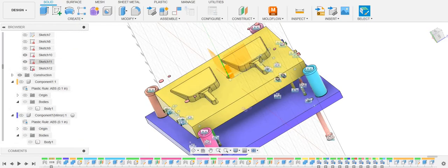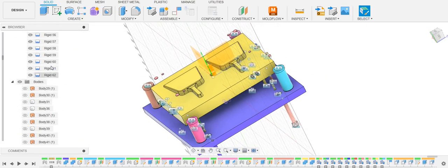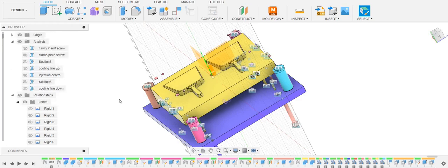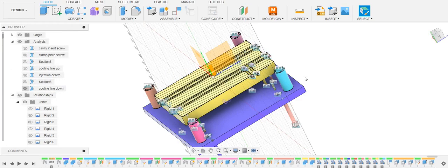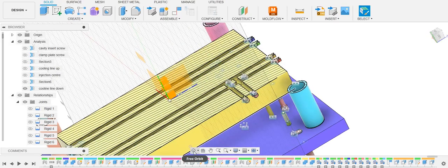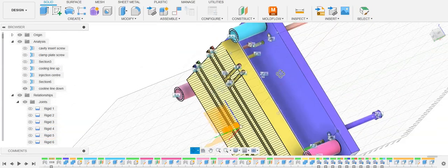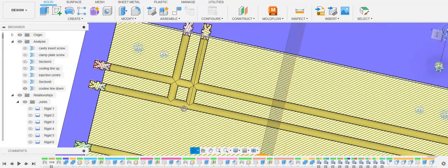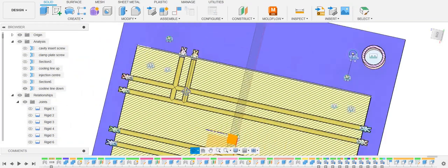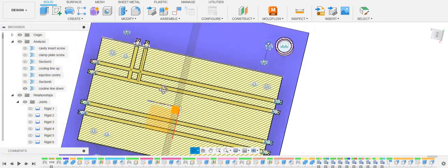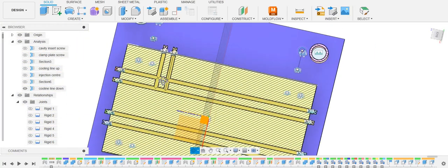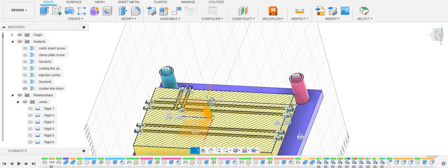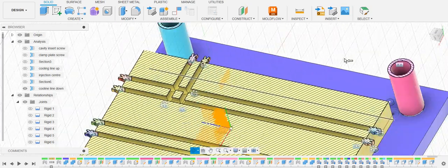We have to fit in the sealing plugs so that the outlet coolant and the inlet coolant don't mix together. So we turn back on the section view we created initially. So we have a sealing plug here and a sealing plug here. The hot water coming from inside will mix with the inlet liquid.